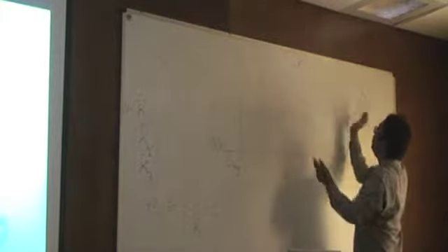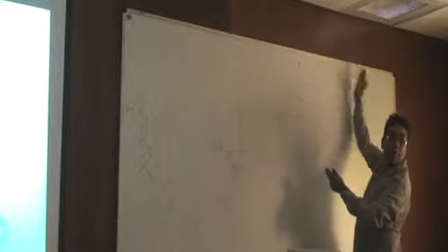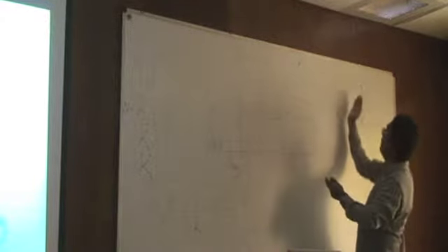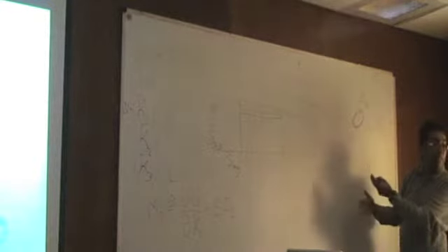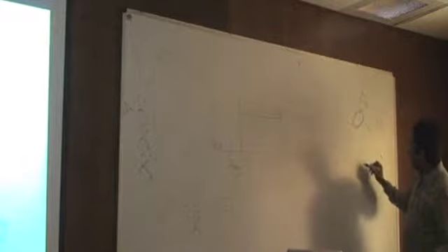Of course, there is a rigid body-like rotation because of this curving up; a cross section over here would probably go over there. But other than that rigid body-like rotation, there is also warping taking place. Not out-of-plane warping, but in-plane warping over here. So a point which was here has now moved to here.